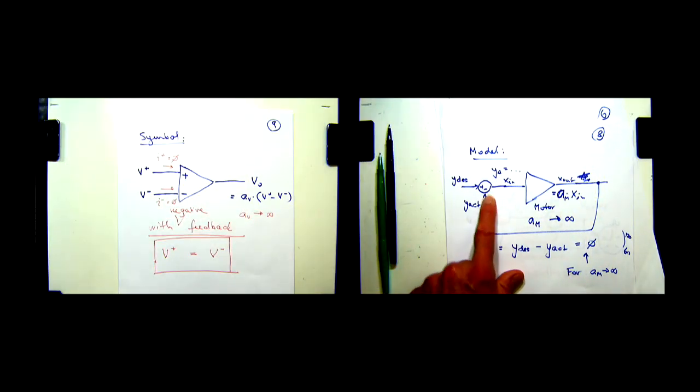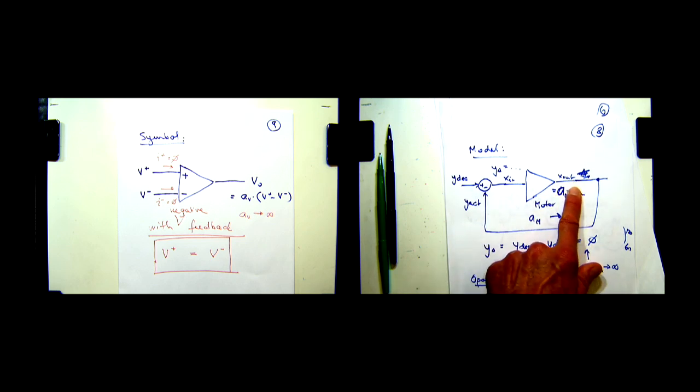No, because of this negative feedback, meaning that if this one increases, then this one here, because we subtract, is going to decrease. So when you do the calculation, to convince yourself, you make AV a variable, and you could make it 1,000 or something like that. Then you don't have this problem where something goes crazy. Then you look at what would happen to this equation if AV would go to infinity, and you will see the correct result or not.